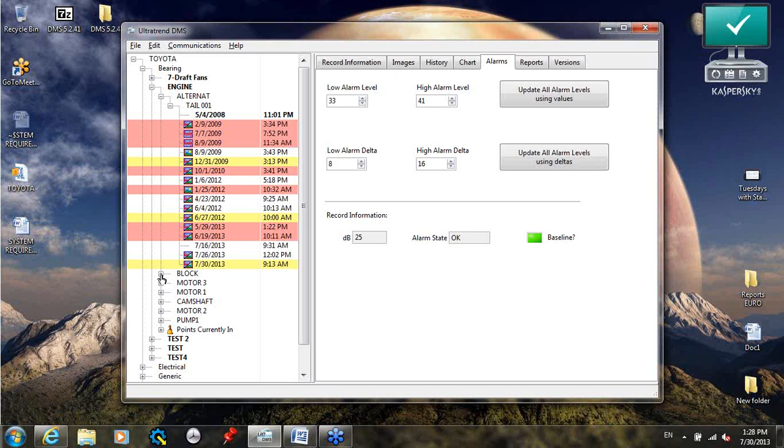That's probably one of the most common questions that we always get asked, is that they have motors, machines that have been running for many, many years. And obviously they're not going to get a true baseline reading. So what the guys can do is a comparison. If they have, let's say, 5 motors that are running the same speed underneath the same load, they can compare them to each other. So if you have 4 motors that are basically within the same ballpark from each other dB-wise, and then all of a sudden you come up to the 5th one and it's much higher than all the rest, then that 5th one is probably bad. You want to try to focus in on that.